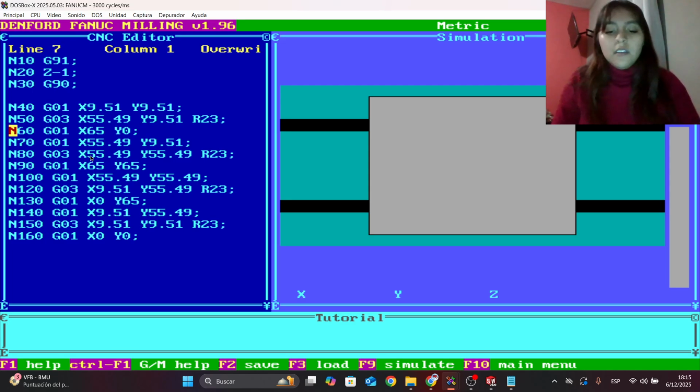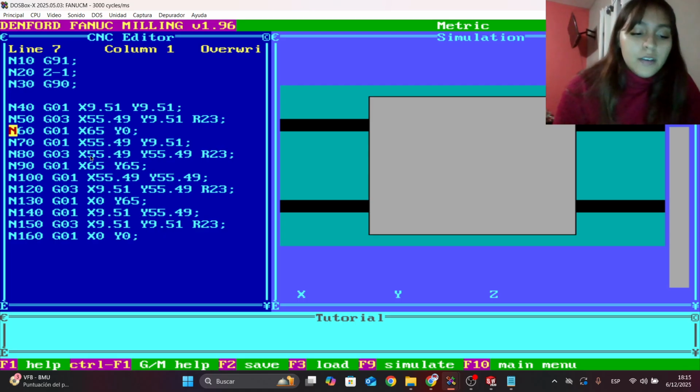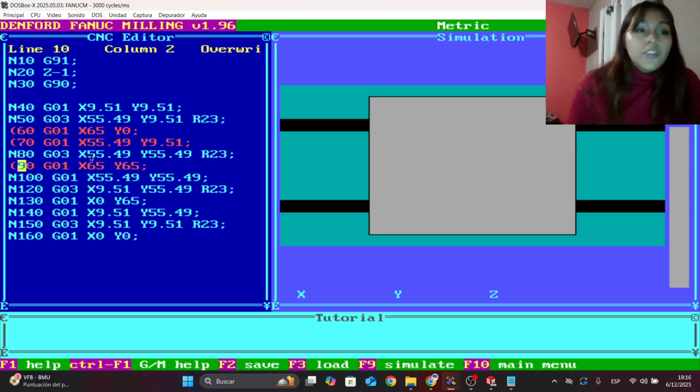I'm not gonna delete it in case something happens, but we're just gonna put a parenthesis to make it a comment. Let's make it a comment of the G01s, and you'll see why I didn't need it.